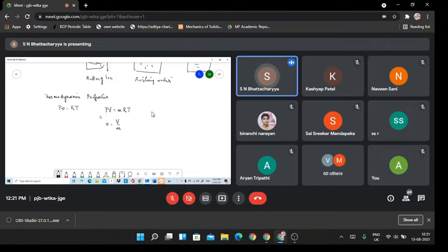Now, it turns out that this is true of most pure substances. So, if I specify the pressure and the temperature, the specific volume gets specified. And then, if I have specified the temperature, the other properties like internal energy and further properties which we'll define, like enthalpy and entropy, also get defined.